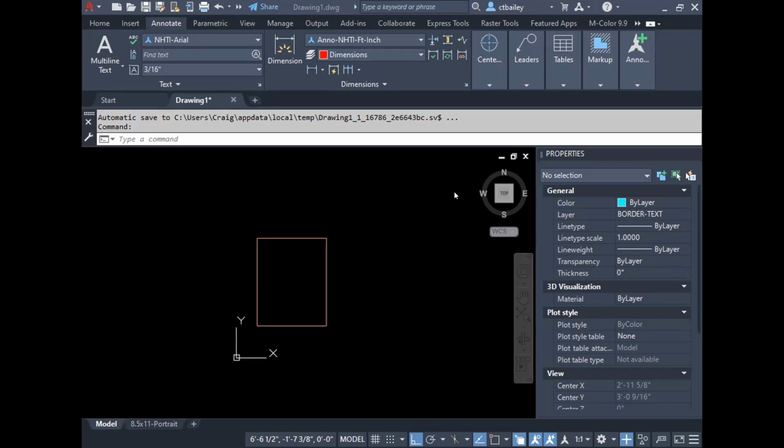See how it's cutting the horizontal numbers? It should be cutting vertical, like up into the width one. So you want this dotted line to be over this? Let me say it again, a different way. The stretch action will translate segments which are wholly contained within the frame. It will then also stretch those segments which are cut by the frame, as if it were a crossing selection.